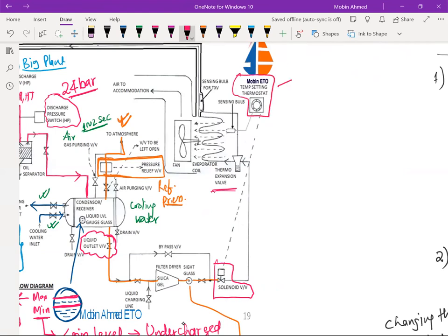This thermostat is there in the AHU, air handling unit. You might have seen it is located here. Generally, it is set at 20 degrees centigrade or 22 degrees centigrade. We'll take 20 degrees centigrade. Now, if it is 20 degrees centigrade, there is also a plus and minus in this. So there is a difference in this, that is 2 degrees centigrade. This difference is by default. We can't change this one. It is a factory setting. Already it comes with this thermostat.